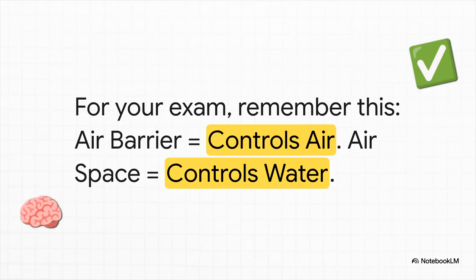You know what? Let's just boil this all down to the simplest possible formula for your exam. If you don't remember anything else, remember this. When you see a question on the PPD or PDD, your brain should immediately go, air barrier controls air. Airspace controls water. That's the mental shortcut that is going to guide you to the right answer every single time.